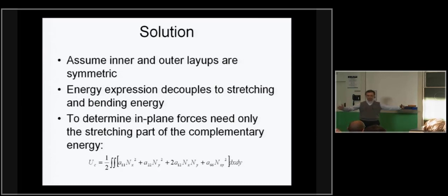If each skin portion between frames is 0.5 meter length, and depending on where you put your stringers, you have stringers every 15 centimeters, let's say. So you can replace even a single bay, 15 centimeters by 50 centimeters, by this, and if you just put a strip of material in the middle to represent the middle layup, you are saving on the stringers and you are increasing the buckling load.